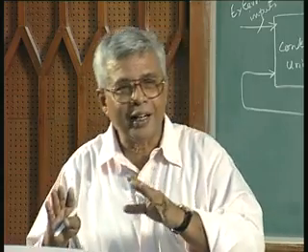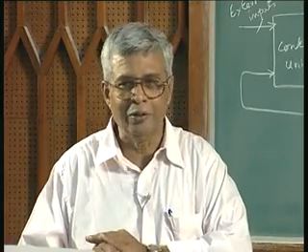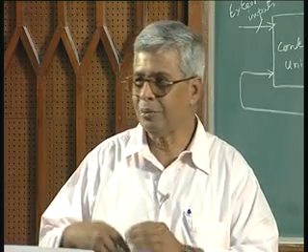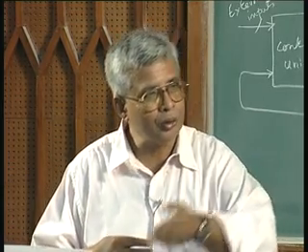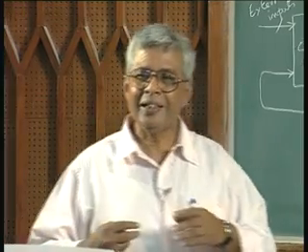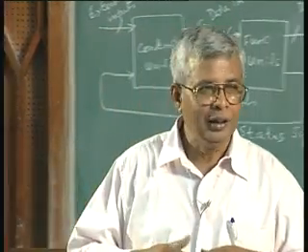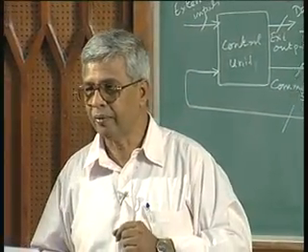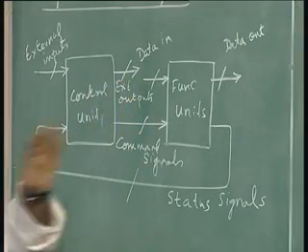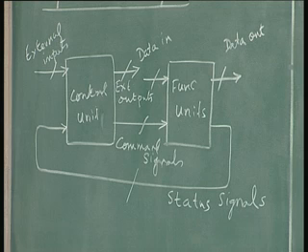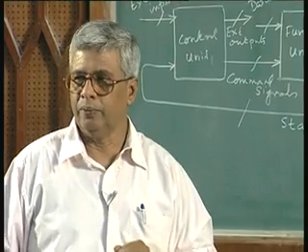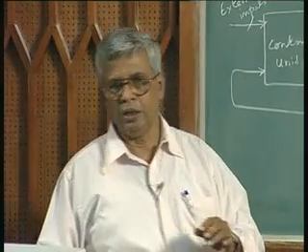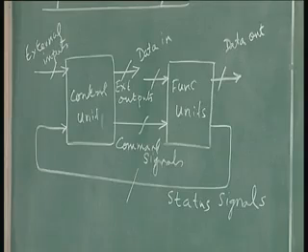Whether it is a Pentium processor or a simple calculator or an 8085 microprocessor, addition is addition. Maybe there are some techniques which make the addition a little faster in the Pentium processor compared to the olden days. Complexity does not come in the functions, complexity comes in the control aspect, because so many things are there to be controlled at the same time and timing has to be very strictly maintained. So, after understanding the problem clearly, partition the problem into functional units and the control unit. Functional units, you list them, see whether they are available, and if they are available, what are the data input and data output requirements, plus what are the control input and status output available, control input requirement and status output requirement, and start your control unit by means of a state graph.